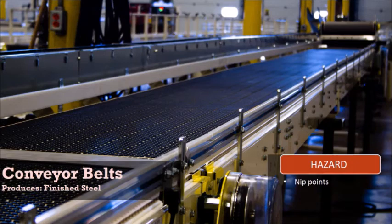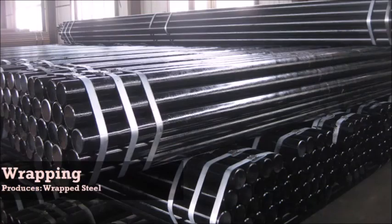When using a conveyor, wear a hard hat and safety shoes. Tie back long hair. Know the location of the emergency shut-off device and how to use it. Do not wear loose clothing or jewelry. Do not climb on the conveyors.